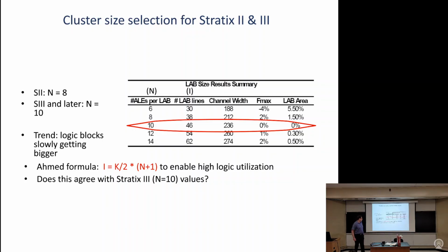Yeah, and in fact, I can do even more. I could use k equals 5. And I got a pretty good chance that I could use all of these in 5-LUT mode if I got some shared inputs. And very good chance I could use them in 4-LUT modes. So yeah, that's exactly, you have to actually think of that. That formula actually works, but don't just think of them as 6-LUTs, because they won't always be used as 6-LUTs. If they're used as 5-LUTs, and you put it in that exact formula, you actually get 52.5, much higher.